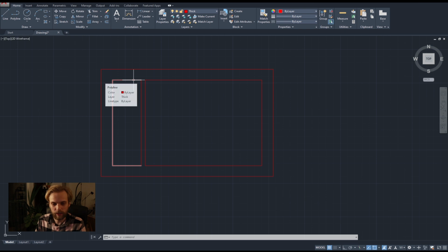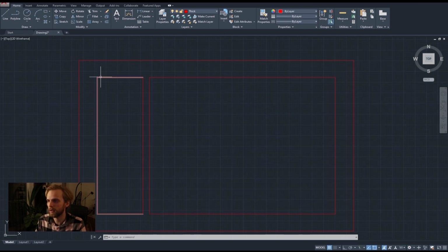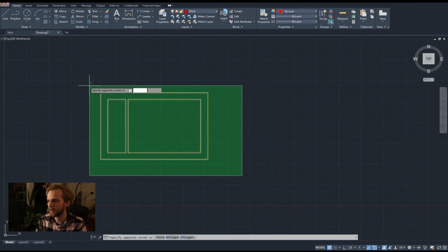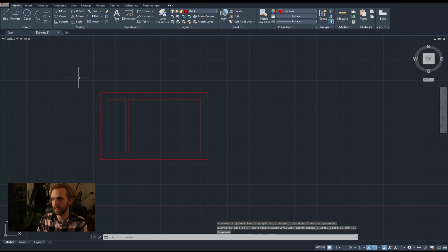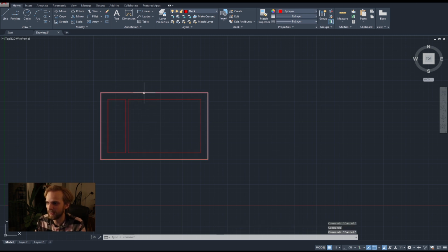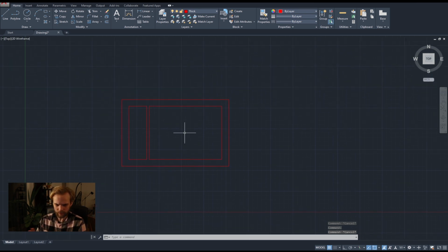This is not clean anymore because this polyline and this line segment are 2 separate entities. I want to join everything up so that this is a rectangle, this is a rectangle, and this is a rectangle, so that I have 3 rectangles here. So I'll select all of it and type in join, hit enter, and yeah, that's it. It just joins them up, right? So now this is a rectangle, rectangle, rectangle, closed. Very important that they are closed. So that is that.